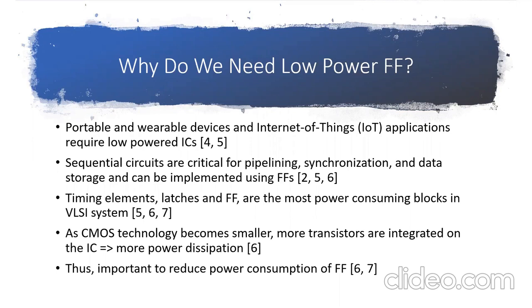But timing elements using the clock network are the most power-consuming blocks in a VLSI system. They can take up to 70% of total power consumption. Also, as the CMOS technology process is getting smaller, there are more transistors integrated on a single IC, which causes more power dissipation. Thus, it is important to reduce power consumption of flip-flops to provide a longer battery life.